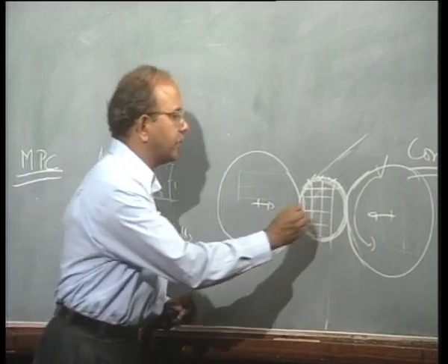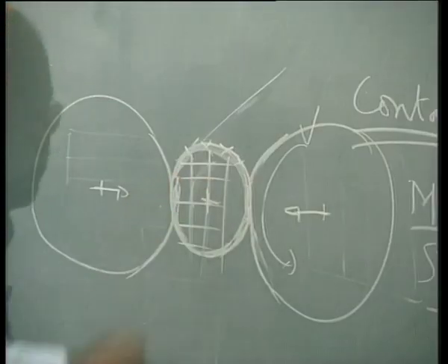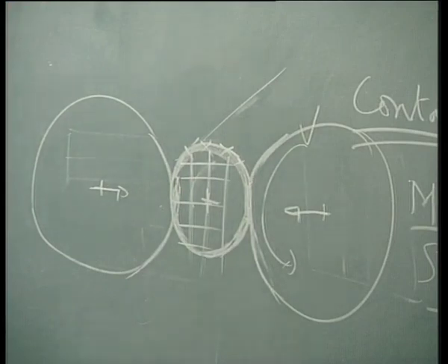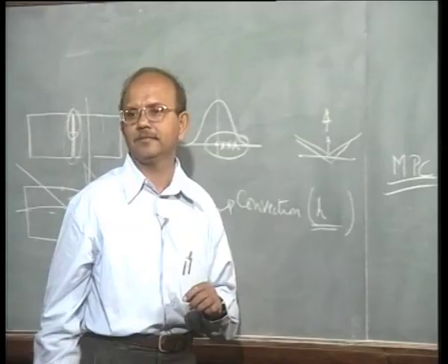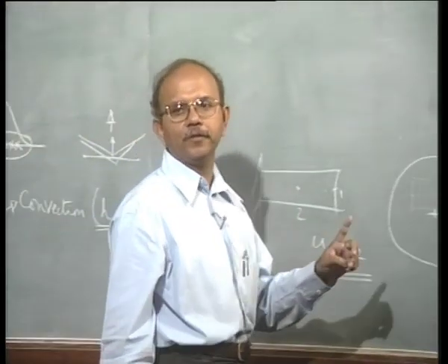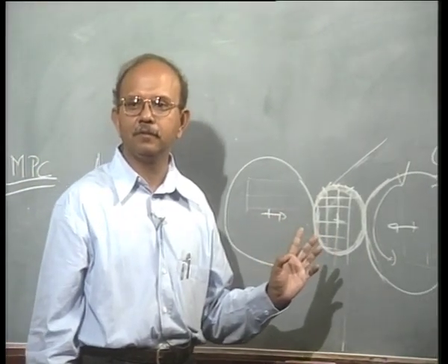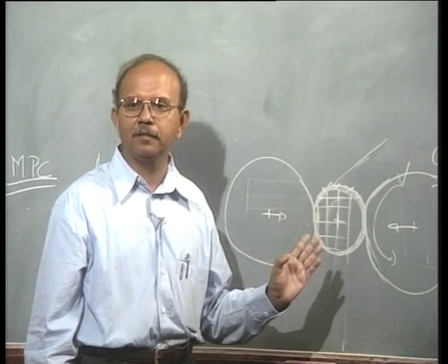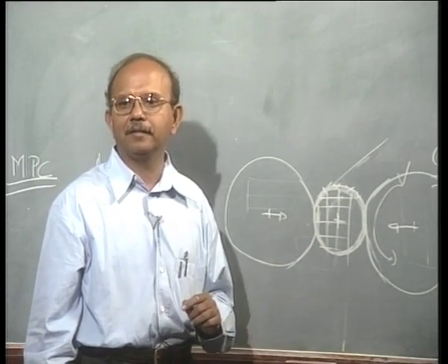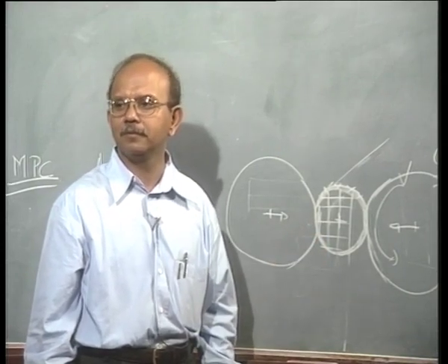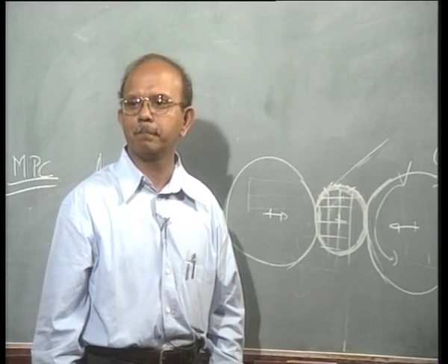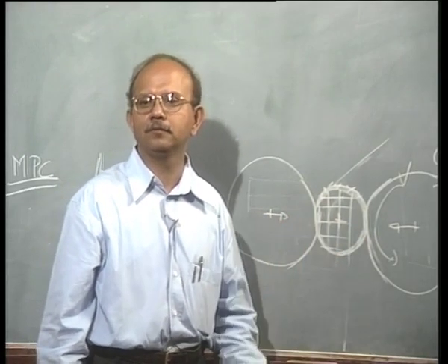Fine. So what you are saying is that the center node here, the node which sits at the center, can be fixed, because that is not going to move. Fine, in the x and the y direction. Okay, I can fix it in the x and the y direction. Is that clear? Very good. Then what else do I do? Can I apply the load now?